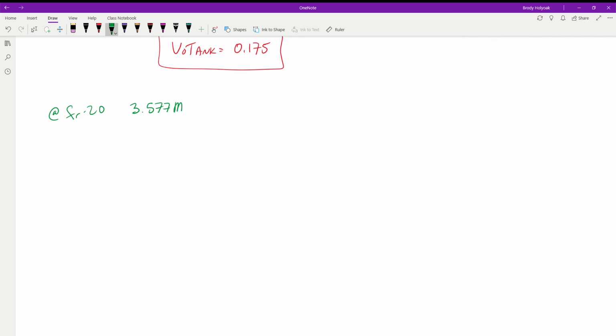that gives us 3.577 megahertz. The XC value is 1 over 2 pi times the frequency times the capacitance. So we have 2 pi times 3.577 meg times the 330 picofarads. That comes out to be 134.83 ohms at negative 90.